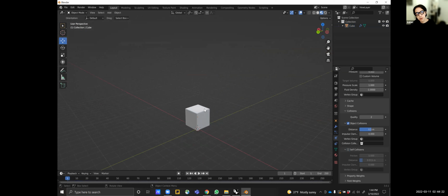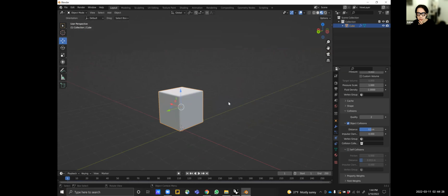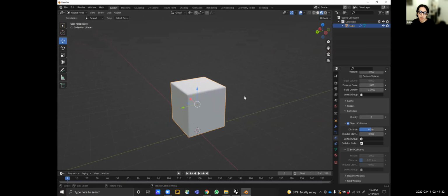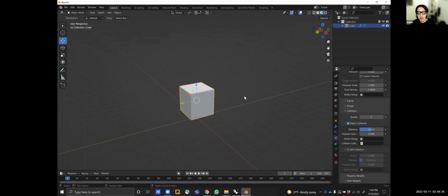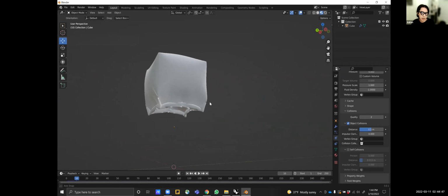I think for inflatables, you can definitely see it, but it's most obvious when you have cloth, like curtains or fabrics, then the self collisions really become apparent. And then the distance settings, like if you put distance all the way at 0, it makes things accurate because the force field is essentially nothing. So things are actually hitting each other. All of that becomes more apparent.